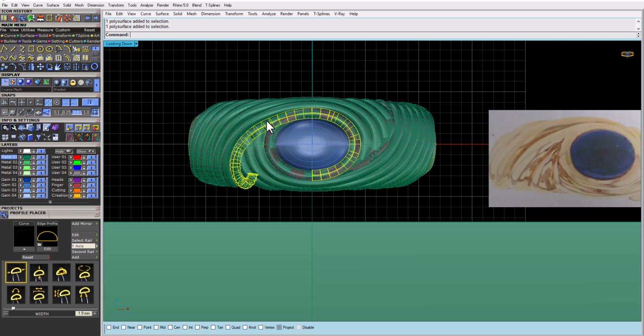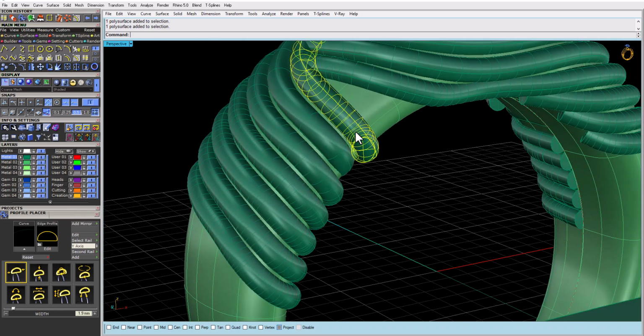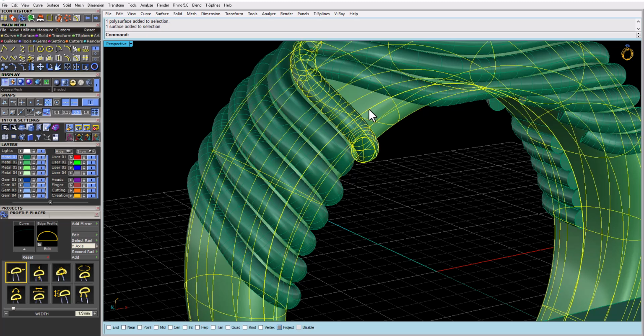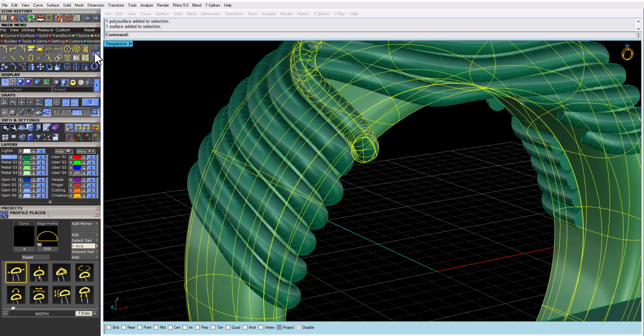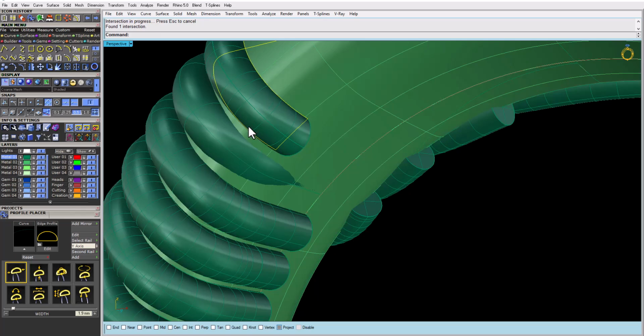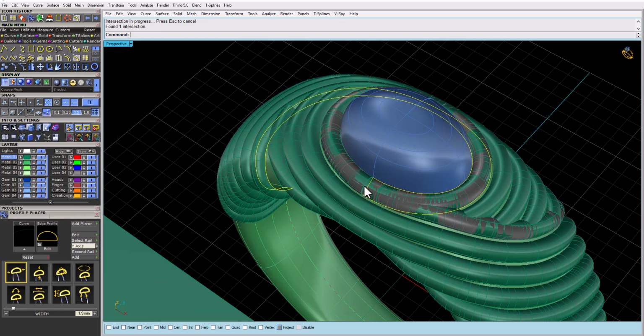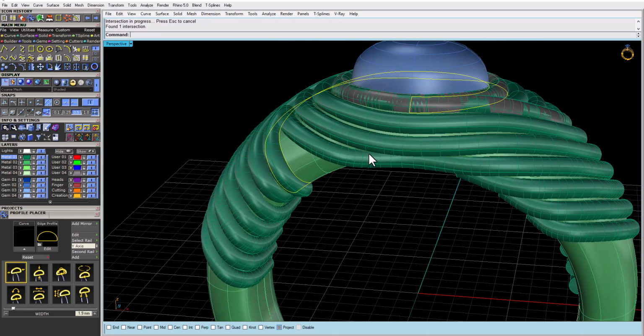Okay, now one thing I wanted to explain and I forgot is you might have a problem with sweep one, so let's do a sweep 2. And to get a sweep 2, this is what I would do. To have a tool rail connected to the surface, I would just select these two surfaces and I would do intersection. So what happens is, as you can see here, we have one rail and the second rail over here, and they go all the way till the end.